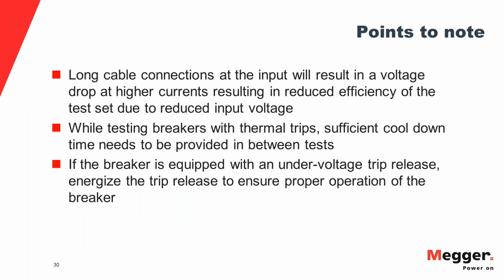So these are the 4 tests that are done as part of primary injection testing. Some points that you need to make a note of is that if you have really long cable connections at the input, that will result in a voltage drop on the input side if you are drawing a high current.